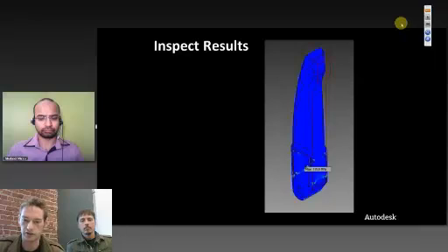So now we've done this example, and we find that the maximum stress on this part is 115.8 megapascals. And I know that that's sort of above our threshold. It's above a factor of safety of 2, which is what we were looking for on this part. So let's see if we can take away some material and see if that makes it any better.